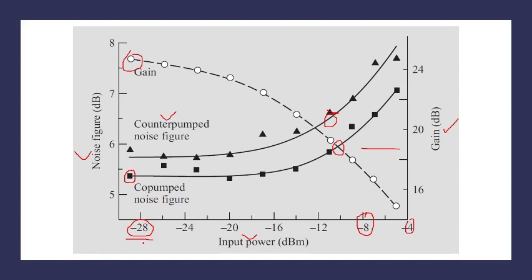So this is a basic phenomenon. We always try to give a low value of input power in an amplifier and transfer the pump energy efficiently to our input signal. If we give a high input signal, the efficiency of the optical amplifier decreases.